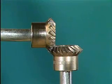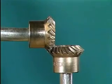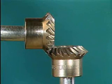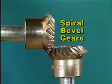Since the teeth engage gradually, the noise produced by the gear set is reduced, and since the gear teeth are twisted, more gear teeth can be meshed at the same time. This increases the load that the gear set can transmit. Bevel gears made this way are called spiral bevel gears.